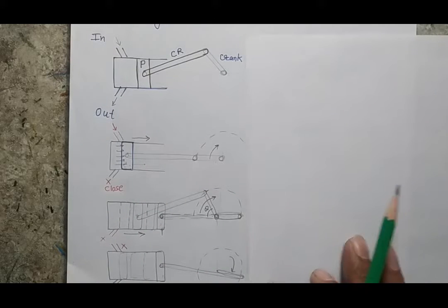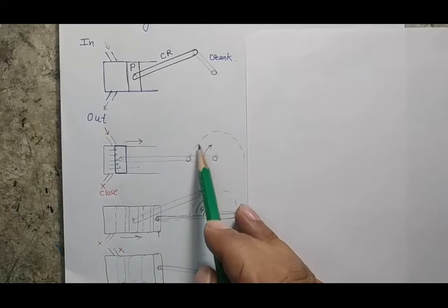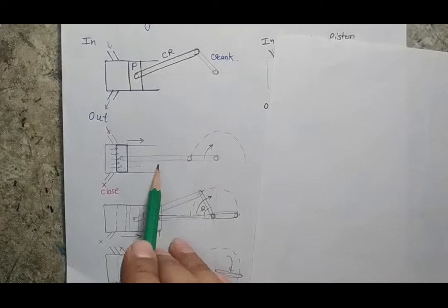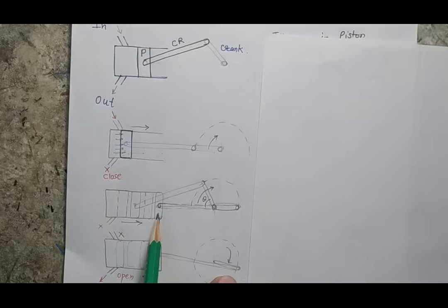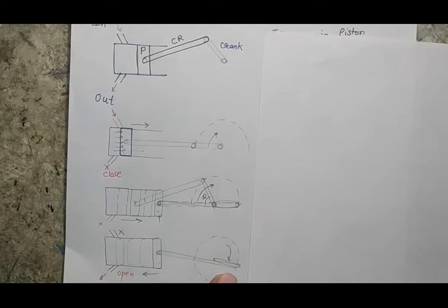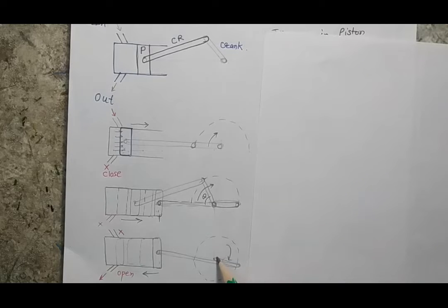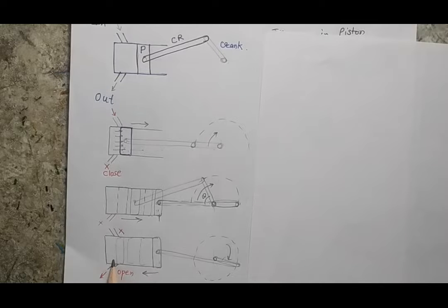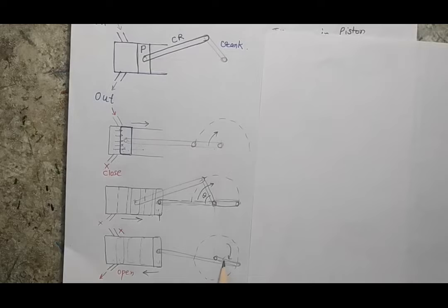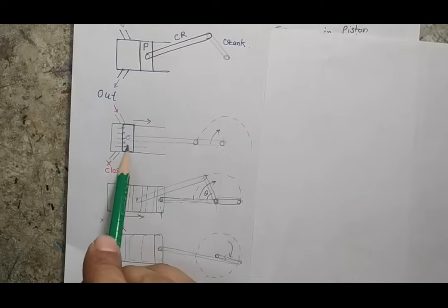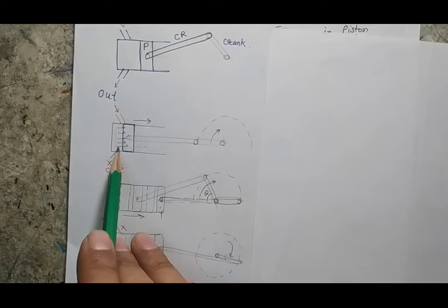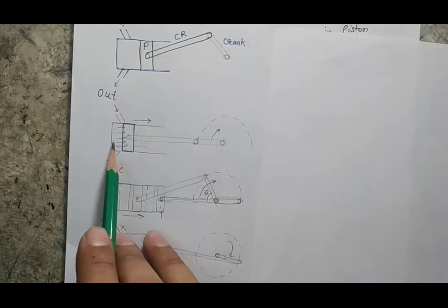So here we can see that for a half rotation of the crank there is power to the system, but for the remaining half rotation there is no power generation, or there is no steam which will give power to my system. Instead, the system has to use its energy to move the piston from the right extreme position to the left extreme position. That means during this period there is a negative torque on the crankshaft, because the crankshaft has to work, and that work comes from the flywheel. But for the motion when there is steam inside the chamber, the system receives certain energy because of the steam.